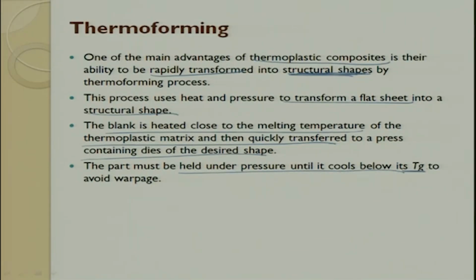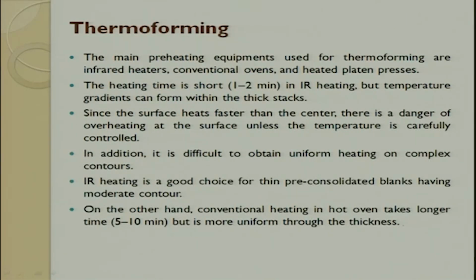If you go back and see, this is what I was trying to explain to you when I was discussing the thermoplastic tape process, the tape winding process, about the consolidation cycle. You try to maintain just below the Tg and only then release the pressure. The heating cycle we use will more or less be the same. Here the equipment is preheated, and then the heating cycle is for 1 or 2 minutes.